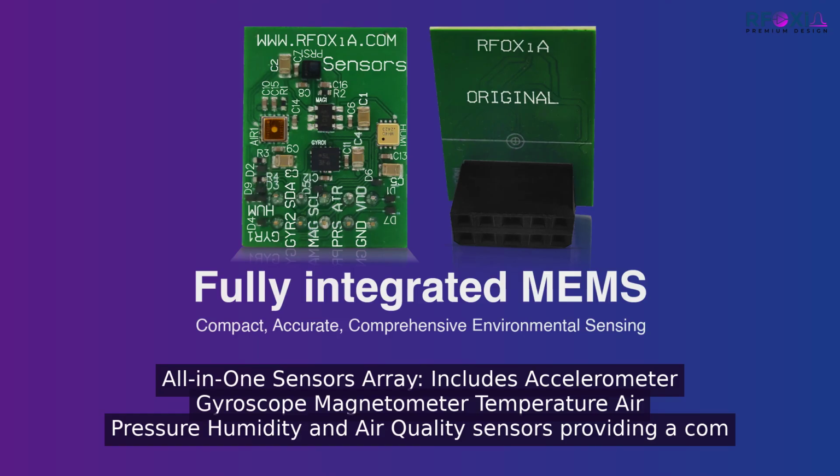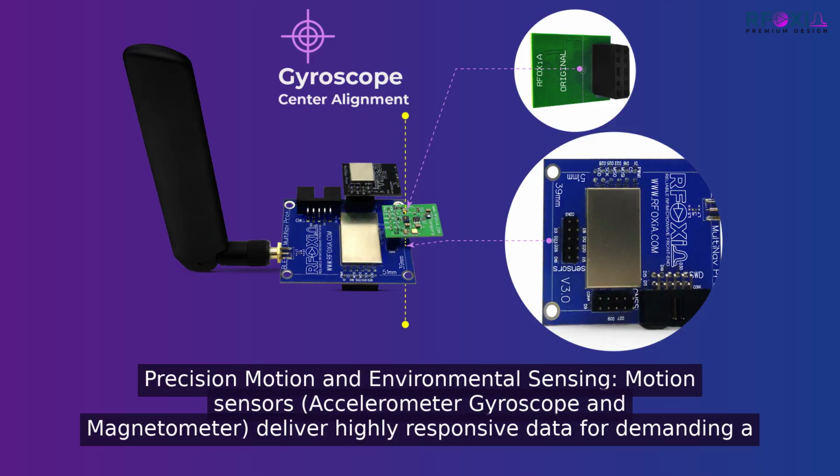This is the Multinav Pro Plus Sensors module, 7 sensors on one board: accelerometer, gyroscope, magnetometer, temperature, air pressure, humidity and air quality, all of them selected and laid out so that none of their I2C addresses conflict with each other. The entire coordination problem is handled before your firmware touches it. The motion and environmental halves of this module serve completely different purposes, which is why they needed to coexist without interfering. The BMI 270, the TMAG 5273 and the LPS 22HH give you the orientation and altitude data a drone flight controller needs at high update rates.